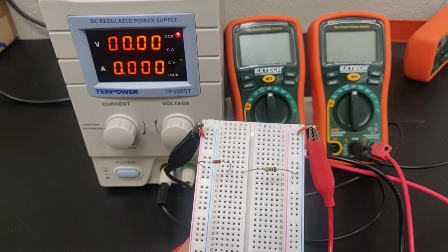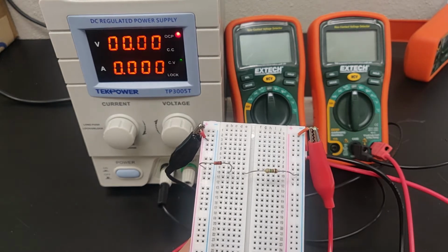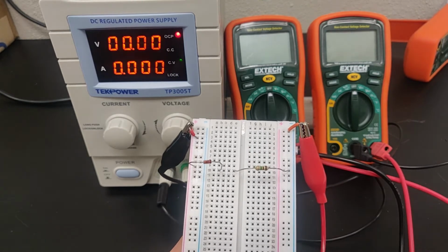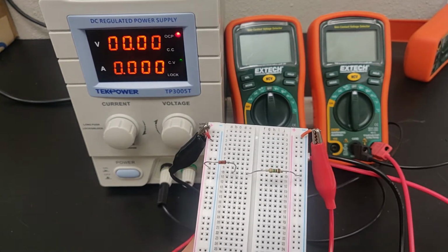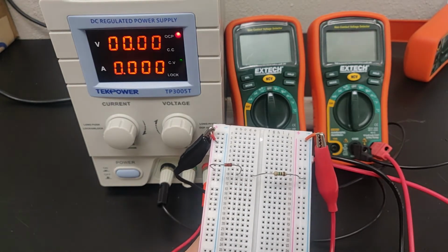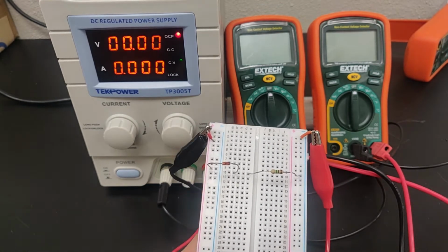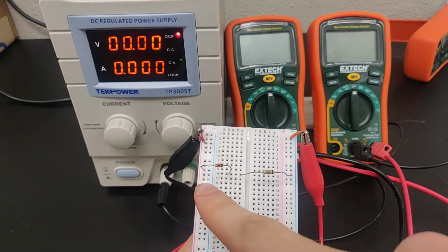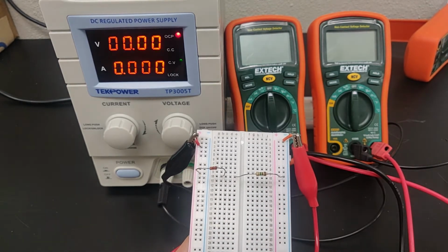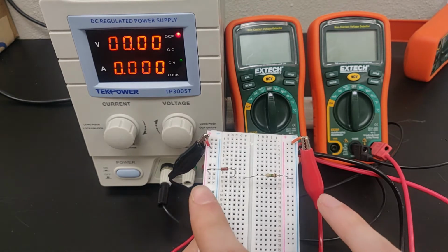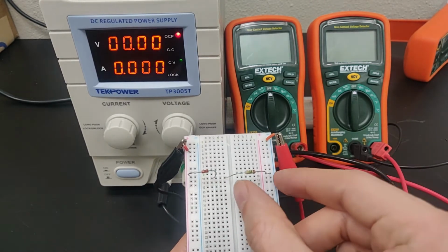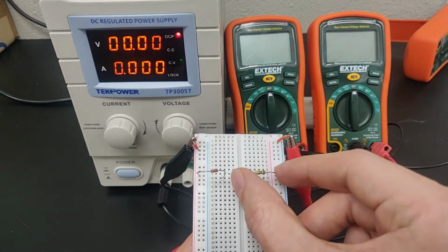But we want to see it approach this point without actually getting to the true breakdown point, because we don't want to break our component. Because of that, the voltage drop over our diode, leading up until it breaks down, is really tiny. So unlike last time where we could very easily measure the voltage drop over our diode and the voltage drop over a resistor, this time we are going to be measuring the voltage drop over the entire circuit, and then we will still be measuring the voltage drop over our resistor.